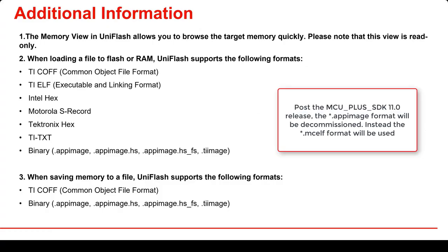Uniflash supports a wide variety of formats such as TI-COF, TI-ELF, Intel Hex, Motorola S-Record, Tektronix Hex, TI-TXT, and binary format. Please be sure to go through the MCU Plus SDK documentation to know which formats are supported and tested.